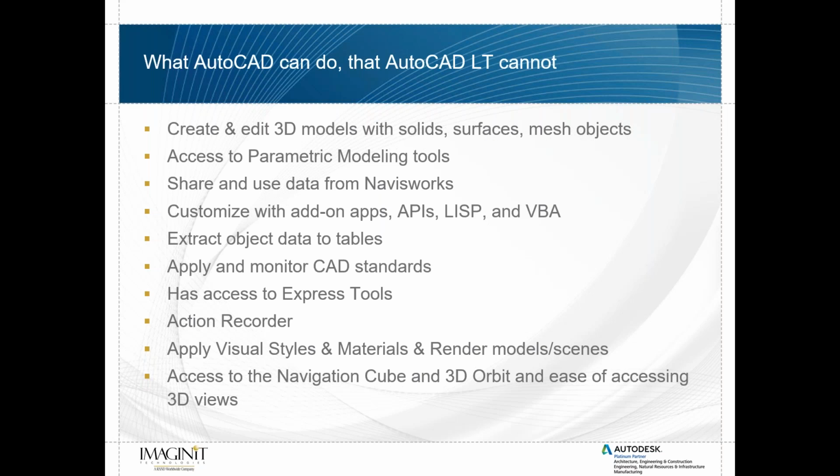You can apply and monitor CAD standards. You have access to the Express tools, the action recorder. The big thing is you can apply visual styles and materials and render models and scenes inside AutoCAD that you cannot do in AutoCAD LT. And you have access to the navigation cube, the 3D orbit, and ease of accessing 3D views inside of AutoCAD that, again, AutoCAD LT cannot do.